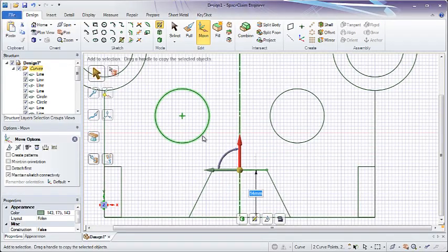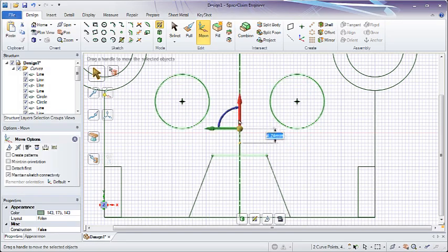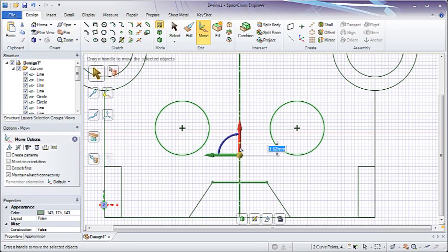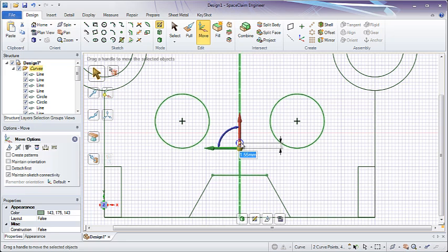Let's say I Control select the two circles, 1 and 2. Now what I'm doing is I'm moving all of these objects at the same time. However, to control exactly where I'm moving and dimensioning one thing to another, it's common to grab the yellow ball and drag it to a new location, or choose our anchor tool guide and select on a new location.